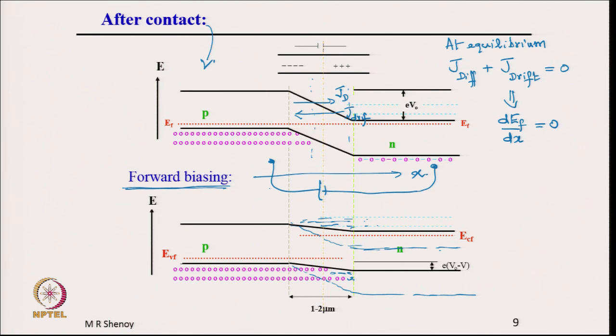Similarly, the holes have also come up to this, and therefore, in the junction region, in this region of space, simultaneously at the same position x, we have holes and electrons. Earlier, away from the junction region, here we had plenty of holes but very few electrons. Similarly, on the n side we have plenty of electrons, the dashed points, and very few holes, which are not even shown. Now, in the junction region, after forward biasing, in the same position we have plenty of holes and electrons, and